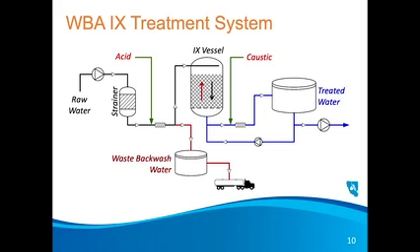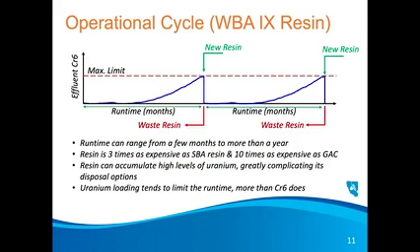The only reason we talk about backwash water here, mainly during installation, just like you heard before about GAC installation, you need to remove those fines. So in an operational sense, you get months to year plus of operation before you have to put in a new resin and dispose of that resin and start a new operation and move on from there.